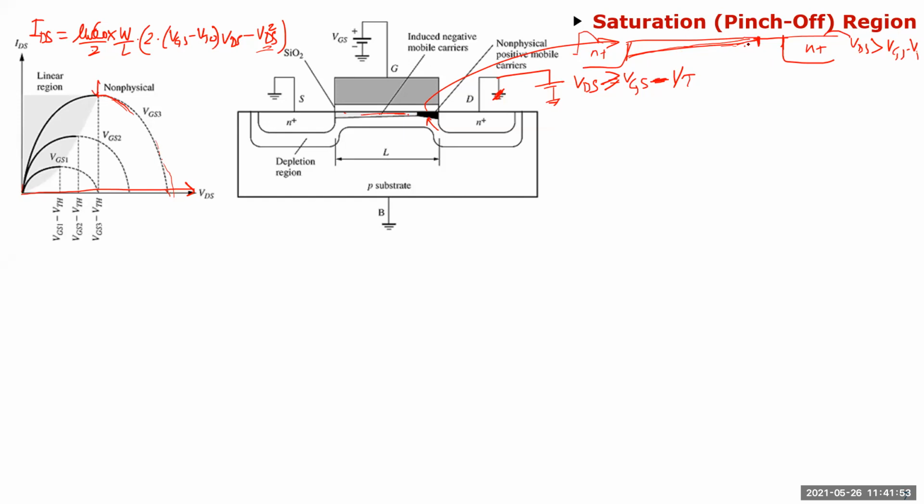And if there is a motion of charge, then this region is actually not very far. Essentially what you have is a depleted area, mobile charges, and a high electric field, so it just punches through. I mean, punches through in the sense that it doesn't destroy it, but it just travels through. So you have current flowing, you have charge, and you have a depletion area. It doesn't stop flowing because there is an electric field which will just push it through. If this distance was really, really large, then you would have recombination and all that, but this distance is small enough for it to just punch through.